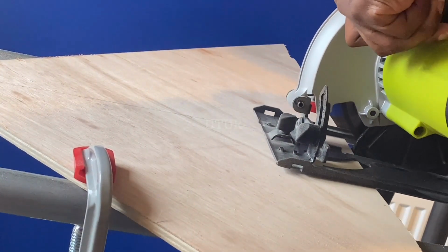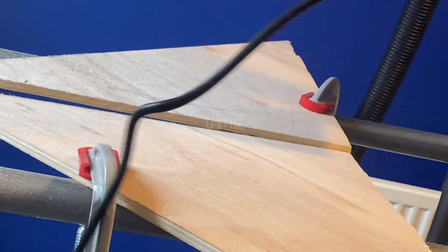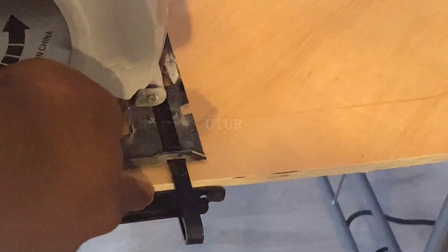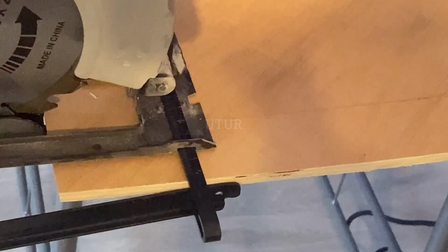So basically when making diagonal cuts, it's basically the same process. You're making linear cuts without the use of the rip fence or the parallel guide, and that's because you can't fit it in the midsection, as opposed to the edge of the plywood board, which provides clearance for us to install the rip fence or the parallel guide to enable me to make repetitive, accurate linear cuts.